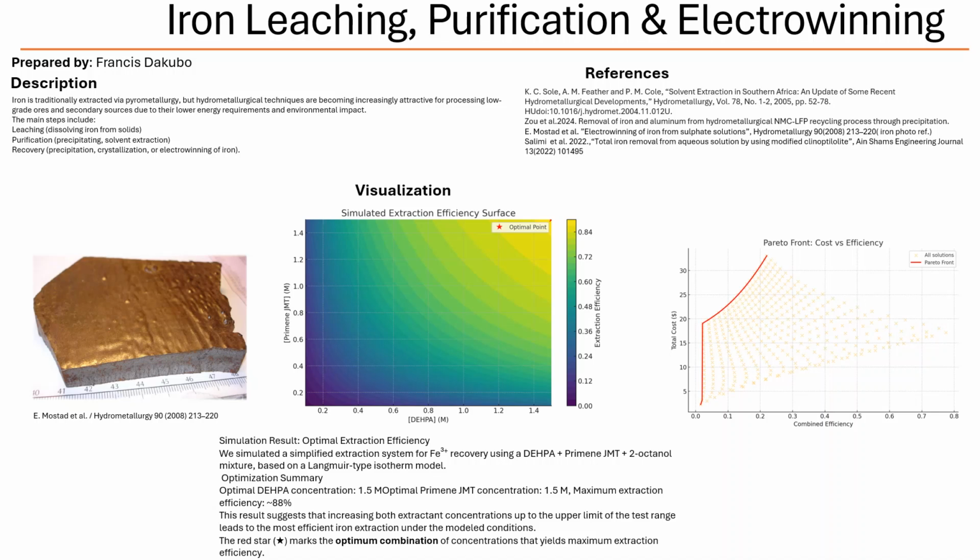Not ideal if you're trying to recover those metals too. Right, it's like catching unwanted fish in your net. Exactly. The conventional jarosite process was patented back in the early 1960s. It involves precipitating the jarosite at those high temperatures using sodium or ammonium ions. The reaction produces acid, which then has to be neutralized, typically using zinc calcine.